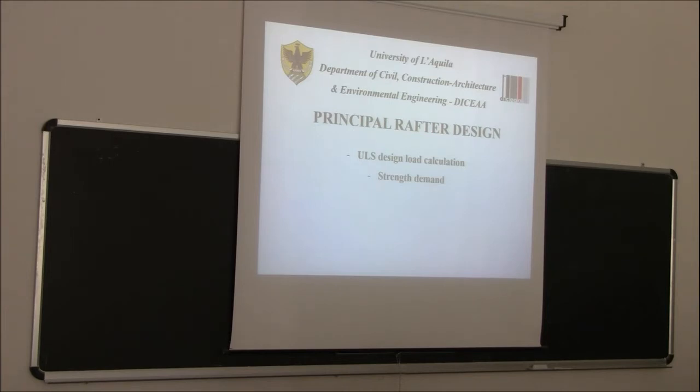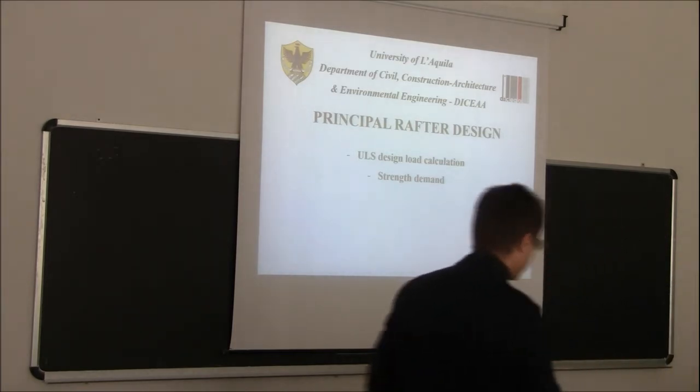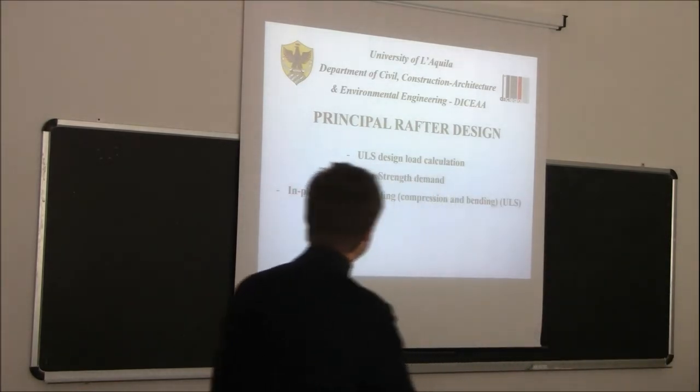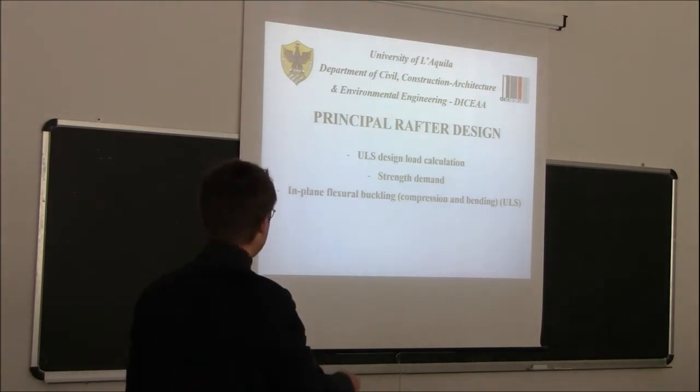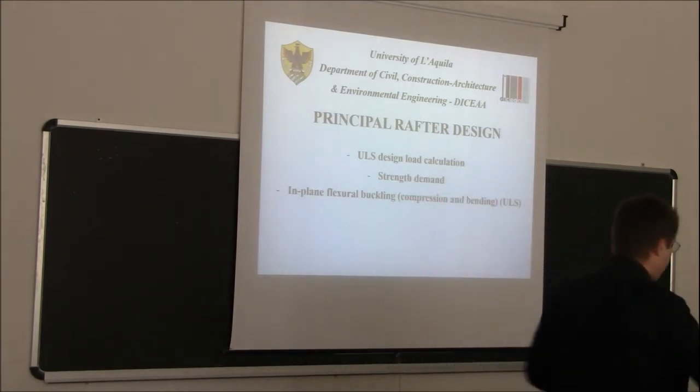Then once we assess the governing load condition, it is a matter of finding out the strength demand. So basically to solve this system, this simple system I would say. Find out the reactions, find out the internal forces. Then we will have to check the principal rafter design for in-plane flexural buckling. It will be, in this case, compression and bending.